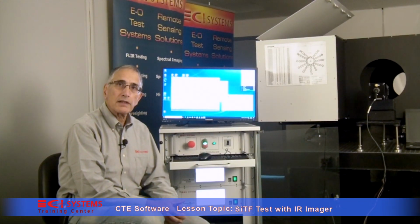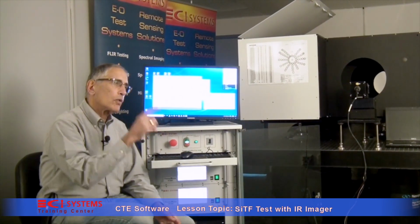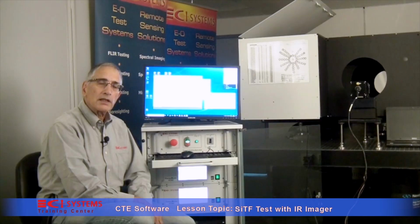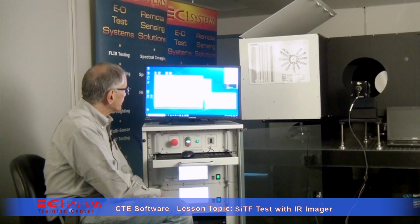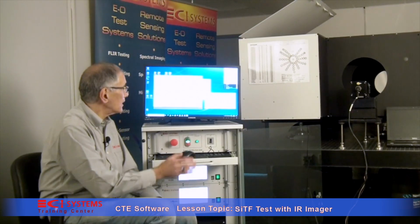Basically what we're looking at in the SiTF is the gain of the imager in the linear range and where it saturates in the plus and the negative temperature zones. We have three outputs here in the system. One is called the out SiTF, or in other words, the gain.